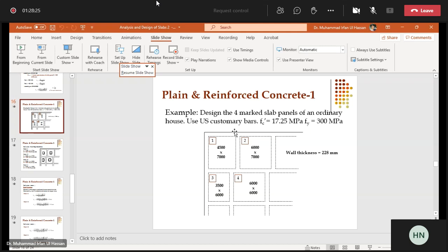That's why you go under the beam, and you need a lot of extra vertical depth to accommodate the pipes. Overall, if it is a 20-story building, maybe you need 40 feet of extra space, but in 40 feet we can make 4 stories. So that's why, and to save cost, sometimes the flat plate is constructed.